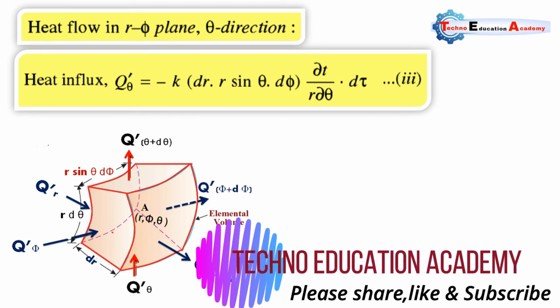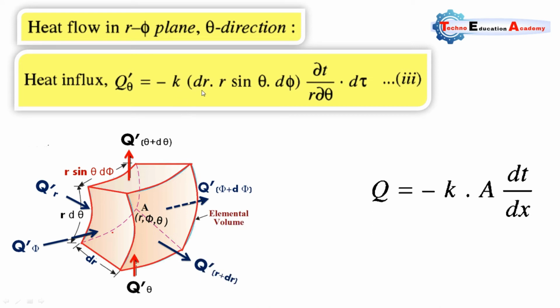According to the Fourier law, q equals minus k A dT by dx. So the area we are considering is the perpendicular area. Means in Fourier law we are considering the area which is perpendicular to the direction of heat flow. So in this direction the area is, here you can see that this is the perpendicular area, dr into r sin theta into d phi.